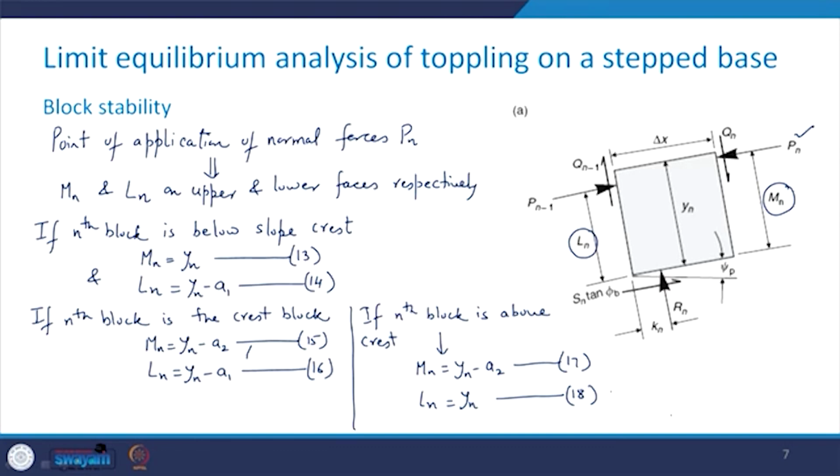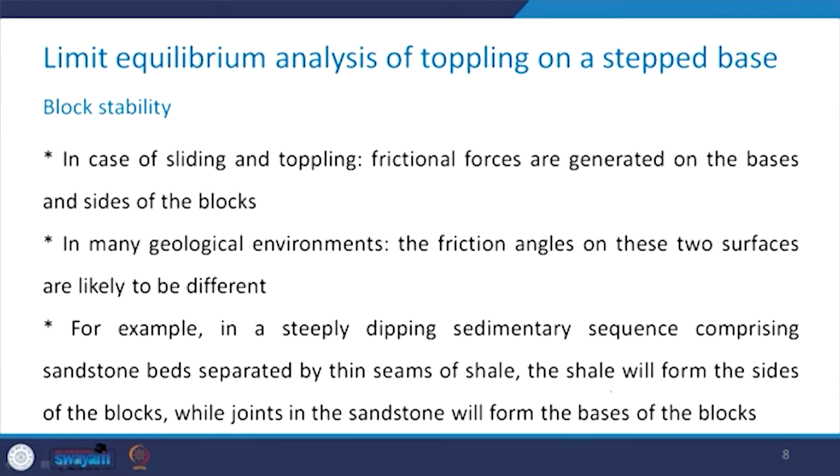Now, in case of sliding and toppling, frictional forces are generated on the bases as well as on the sides of the blocks. In many geological environments, the friction angles on these two surfaces are going to be different. For example, if you take the steeply dipping sedimentary sequence which is comprising of sandstone beds and separated by thin seams of shale.